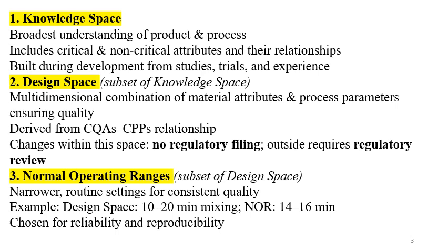It is possible in rare cases that 14 minutes or 16 minutes may happen, and 14 or 16 minutes instead of 15 minutes may not affect the mixing. So you fix the normal operating ranges as 14 to 16 minutes and your target will be 15 minutes. It is selected for the reliability and reproducibility. So this slide you should understand and remember, regarding the knowledge space, design space and normal operating ranges.